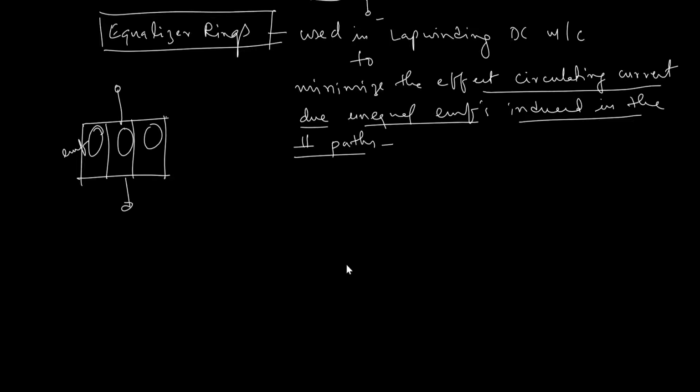So to eliminate or minimize the effects of these circulating currents, we use the equalizer rings.